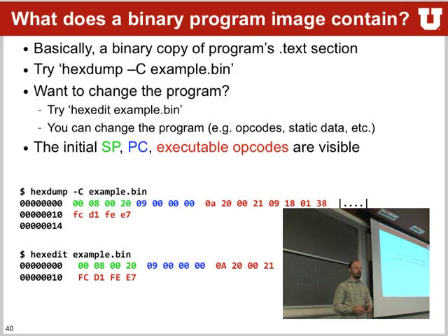So then, what does a binary file have in it? So once you send it through objdump, you can look at it again, and no big surprise really, right? We have the stack pointer, the first jump address, and after that comes your program. It's going to be sitting in code and gets executed as you tell the machine to do.